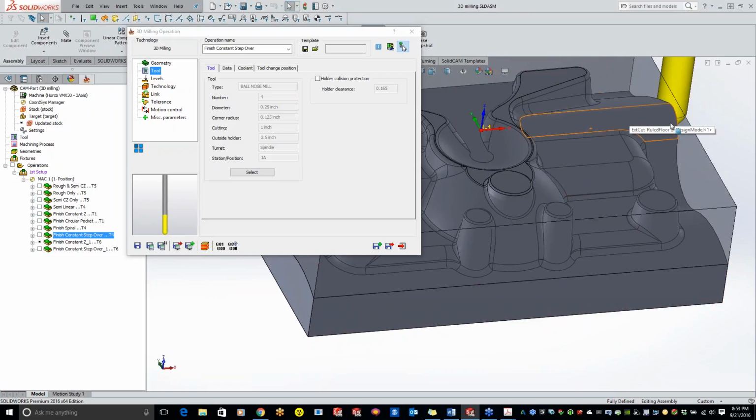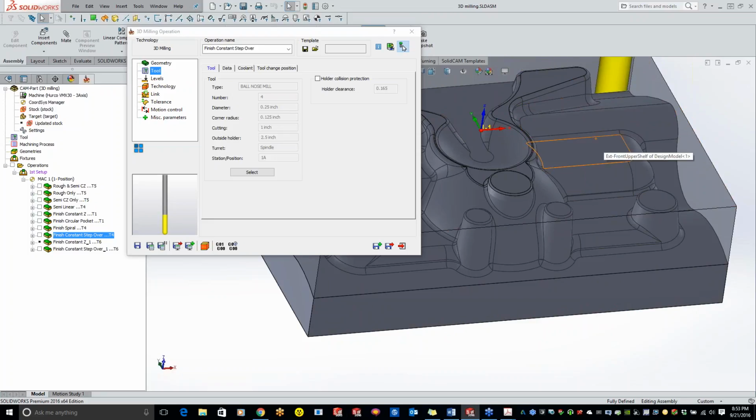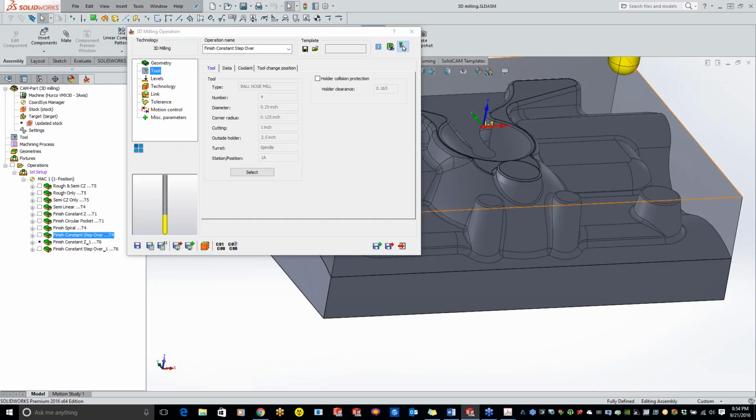But as it is right now, it's a constant feed rate going all the way through, so that feed rate isn't going to change. The only time the feed rate changes constantly is if you're roughing it out using 3D iMachining. I haven't heard much, but I know there is talk of a 3D iMachining finishing path that will speed up and slow down to account for the areas, but it's still out in the future, so don't hold me to that, Dwayne, because I know you will.